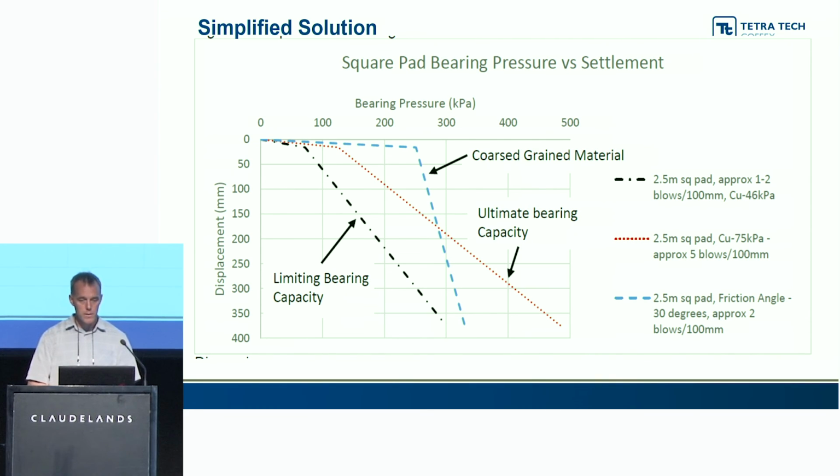I think the reason this is important is the original testing of around 3 blows per 100 mils was probably technically correct for bearing capacity, and if everything was okay, produced about the right level of settlement. But it kind of ignored the classic geotechnical fudge factor of 1/2 and 2, as in if you have any variability on your site, you're quite exposed to getting excessive settlement. If you go from 25 mils and you double it, you're at 50 over here, and you could be at 10 or 12 over here, and suddenly you've got 30 plus mils of settlement. So this factor of 2, in theory, should have helped reduce some of those issues.